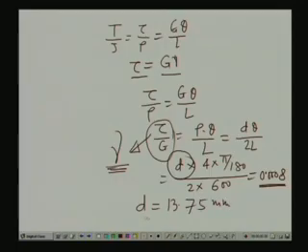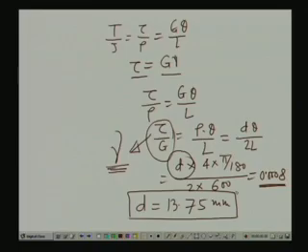Now, please note here that in this particular case the strain of the bar was limited, that because of the application of the twisting moment, the strain cannot exceed beyond a specific value. To limit to that particular value of the strain, you have to find out what maximum diameter of the bar you can use. As we can see from here, utilizing the relationship between the torque and the stress and the relationship between the stress and the strain, we can find out how much diameter of the bar can be used.